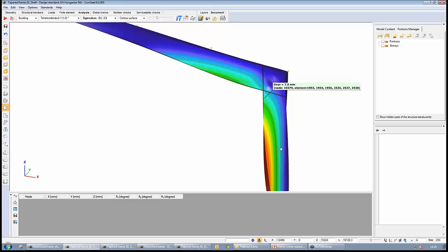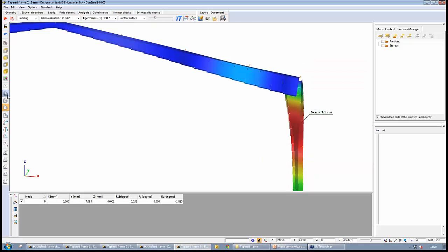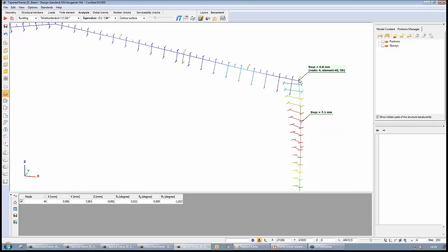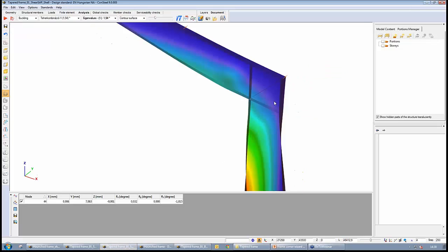and in the beam model the column is going up to this point. We can see that the column line is going to here, and there is a huge eccentricity from the theoretical node to the compressed flange, and this compressed flange can rotate not freely but more freely than here. So the compressed flange in the beam model is not connected to the compressed flange of the beam and column here.